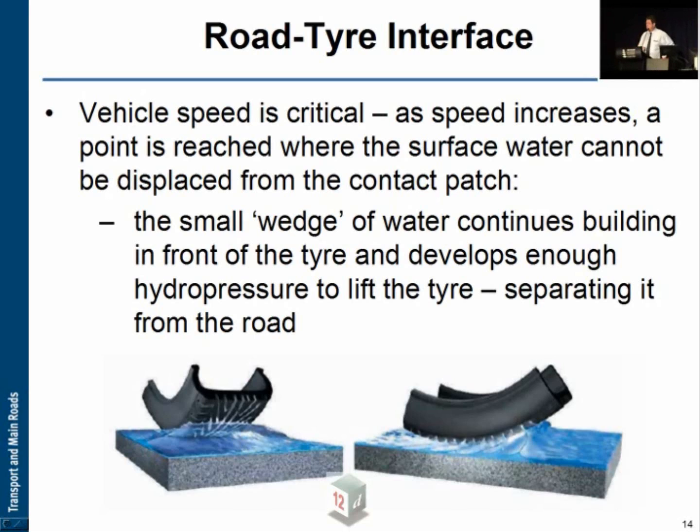So this wedge of water, they call it, builds up and continues to build to a point where the hydro-pressure is enough to actually lift and support the vehicle. And it will stay there until the vehicle slows down or the water dissipates and thins down, and then the adhesion or something like that can grab on again.